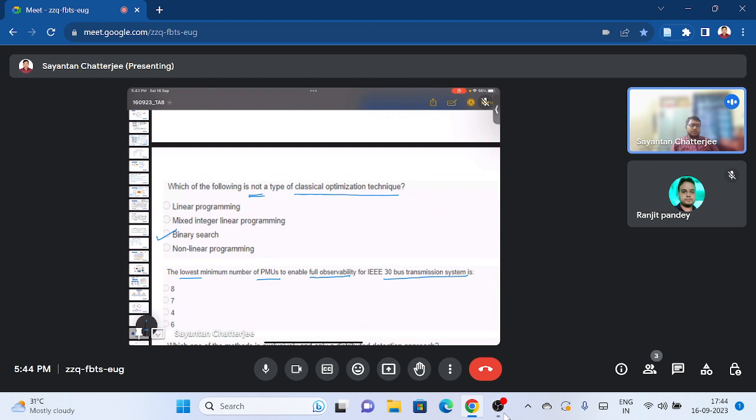On the basis of transmission system reliability, by implementing 3 to 4 PMUs in the IEEE 14 bus system, the entire system becomes observable. Observability criteria means each and every place of the system should have that much facility to monitor the entire system.